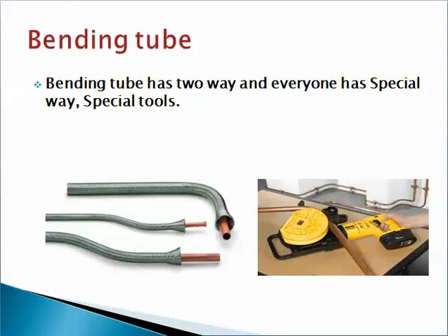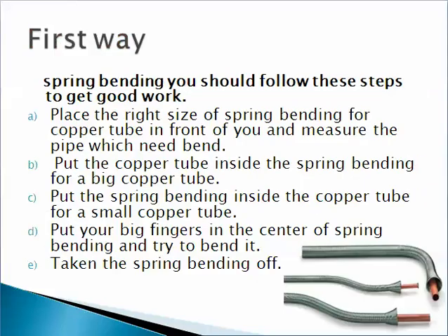I will continue with the two ways for bending tube. First way, spring bending. You should follow these steps to get good results. A. Place the right size of spring bender for the copper tube in front of you and measure the pipe which you need to bend.